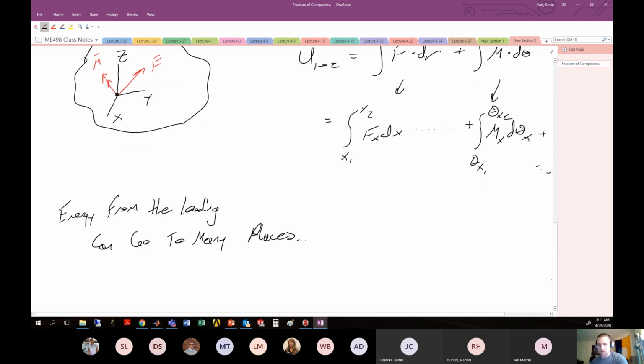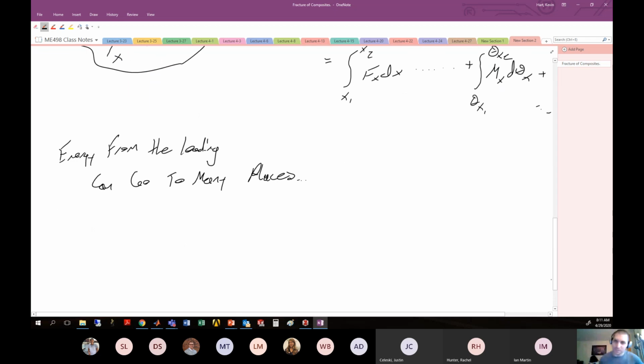The ones that we'll talk about, and the important ones for us, are elastic strain energy, usually denoted with the variable U_E. This is the energy of elasticity, and this is energy which is recovered after loading. Think about a rubber band. You pull on a rubber band, you've externally loaded it. Once you release that load, it responds.